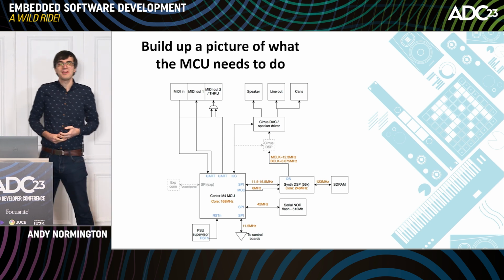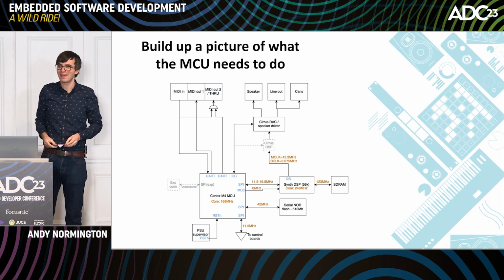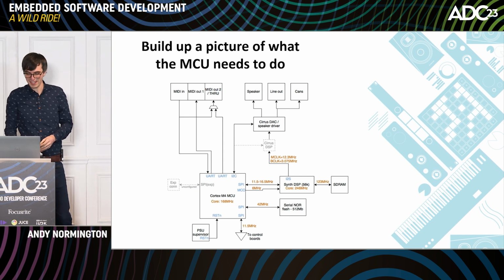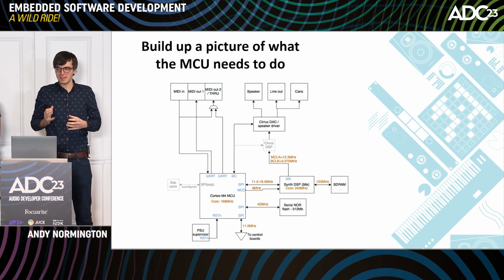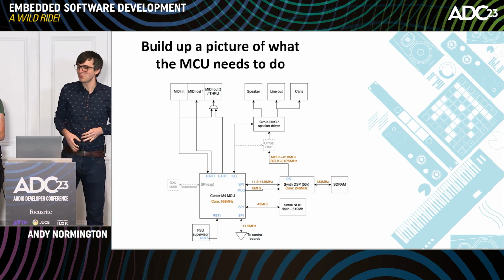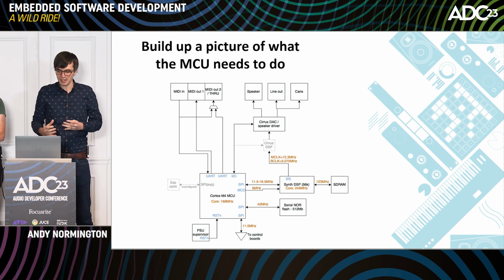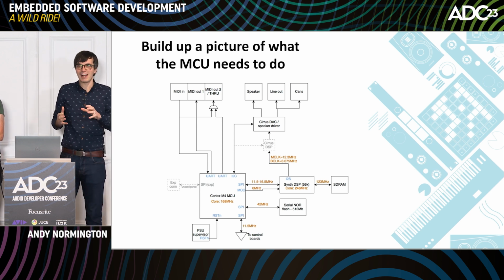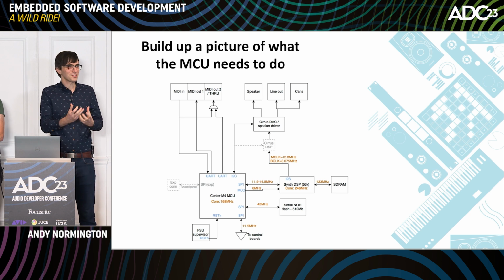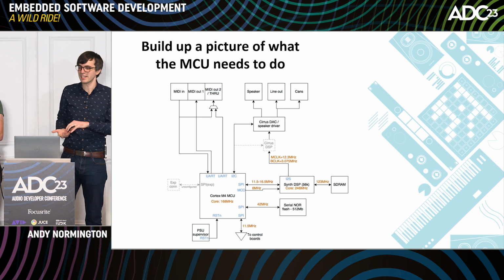So I'm going to take you through how we get from that somewhat overwhelming set of choices and variables that go into choosing a microcontroller towards a platform that we can build the product on. The electronics hardware design really drives all the choices we've got to make here. That defines what we need out of the microcontroller. So we'll start there. We'll start at the beginning of this process, working really closely with the electronics team, figuring out how to take the set of product requirements, what's the user actually going to experience, and turn that into a specification for the hardware design.